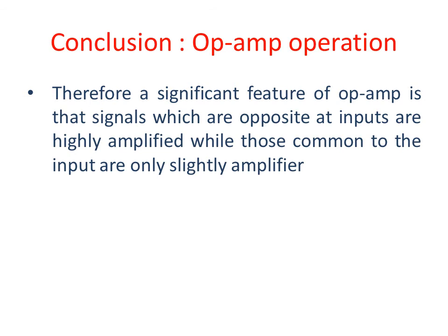But in the third case, the double-ended common mode input, when we applied similar signals to the OpAmp terminals, they in each case resulted in a 0 volt output. So what we can say is that the operational amplifier actually amplifies the difference of the input signal or the differential input signals. However, it actually nullifies the common input signals.